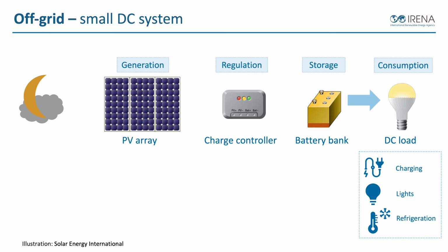Now, one of the downsides to a really simple system like this, if we leave the consumption on too much, we could actually drain this battery down to a point where we could do damage to our battery. Sometimes we may want to add extra protection in there in the form of what we call a load controller. We want to protect the batteries from overcharge, but also from over discharge.